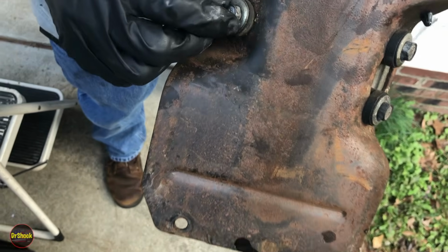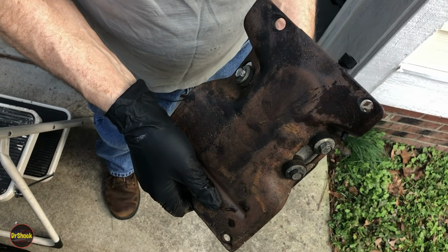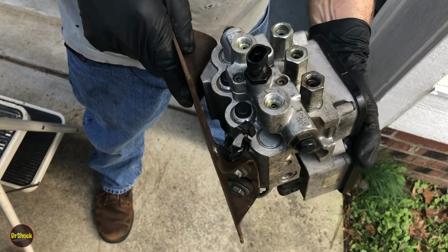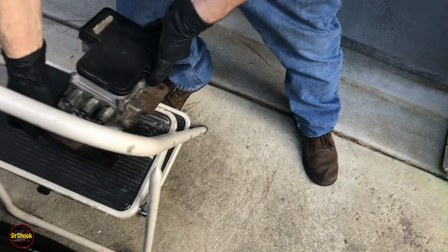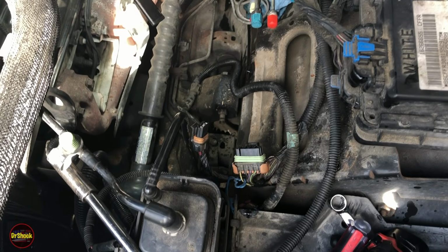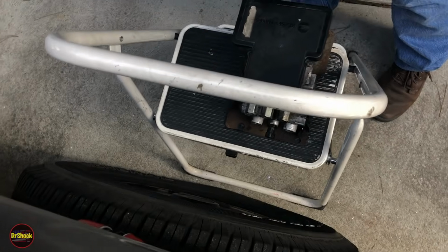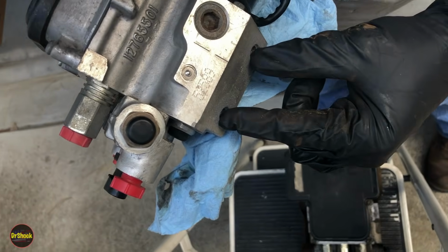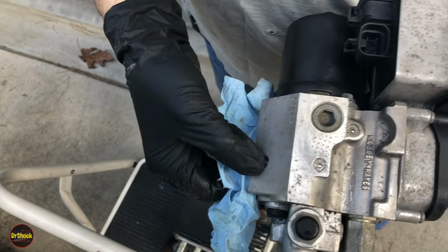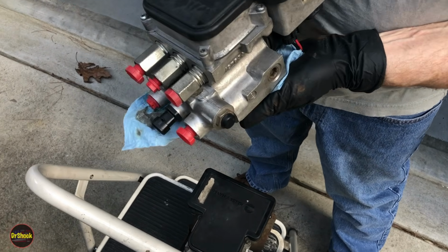If we come over here, we got to take these three 13mm bolts out in order to release the EHCU from the mounting bracket. So if we think about what we were looking at before, if I just set this on this stool, go get our replacement unit. Right, our replacement unit is going to mount to the bracket with those two 13s and bushings on this side and a single 13 and bushing on this side.